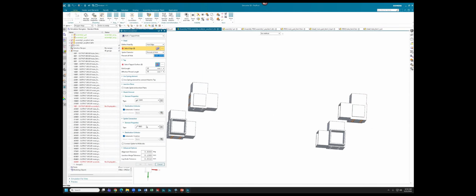Then you will usually have some sort of joint element connecting those spider elements, often represented with a bar element or a spring. That essentially represents the overall stiffness of your total joint.